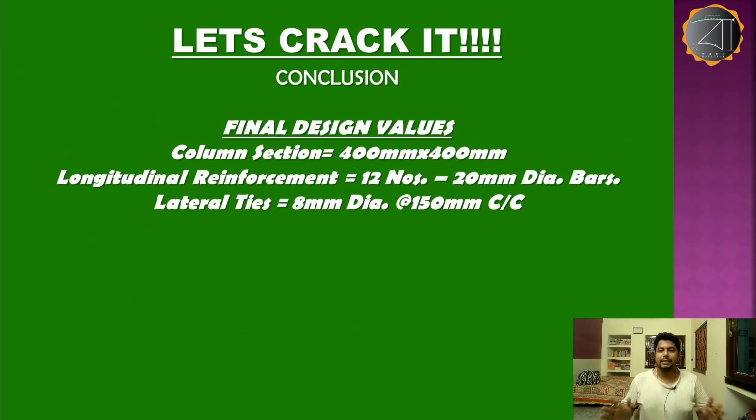So, final design value what is coming up is that column section is 400 mm by 400 mm, or 300 mm by 500 mm. If rectangular sections were provided, then the requirement and distribution of these longitudinal bars would have changed also. Longitudinal reinforcement is 12 numbers 20 mm dia bars, and lateral ties are 8 mm dia at the rate of 150 mm center to center.